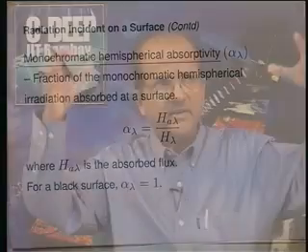All right. So, there is irradiation falling on a surface, H if it is all the radiation, H lambda if it is the monochromatic value that you are looking for, a certain fraction out of it is absorbed. In the first case, the fraction absorbed we call the total hemispherical absorptivity, denoted by the symbol alpha. In the second case, when it is monochromatic, we call it the monochromatic hemispherical absorptivity and denote it by the symbol alpha lambda.